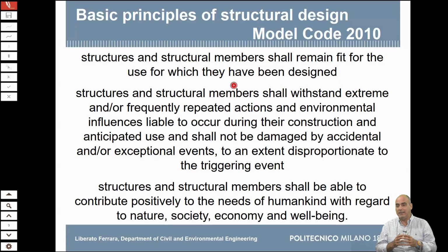Whereas what is called the serviceability condition is something that happens. So in some cases, or better, from a certain point of view, designing for serviceability is even more important than designing for ultimate limit states. We have to check both, but we have to bear in mind that ultimate limit state, which pertains to safety, is something that we do not want to occur. Serviceability limit state, which pertains to use, is something which happens. So the structure experiences those conditions 24 hours a day, 7 days per week.